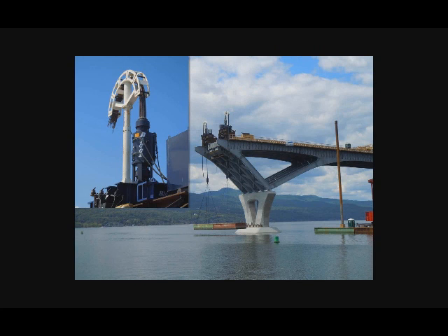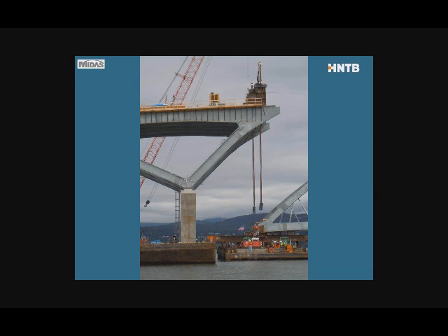wedges, deflates the piston, resets the rear wedges, jacks up a little. This is how very heavy loads get lifted, and that white assembly is just to keep the strands from kinking, just to deviate them. This is a trial lift, so this is just dead weight in the front. Normally that operation should go rather quickly. A foot an hour shouldn't be a problem. Should be faster than that.